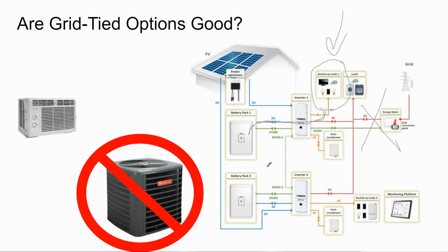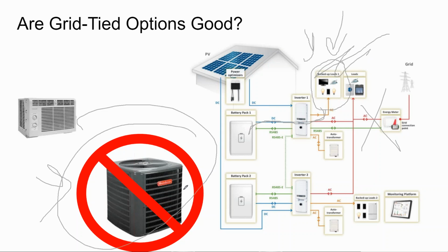And so there's costs associated with rewiring your service panel, which is just doing rework. It's not adding new stuff to your home. It's not whole house power. It's just powering a few things. And then, maybe this is the southerner in me, but when the power goes out, the thing that I want to keep going is the air conditioner, and these critical load panels from the Tesla Powerwall and from SolarEdge are not powerful enough to run a central air conditioning unit.